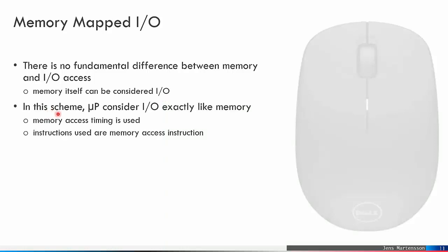In this scheme, the microprocessor considers I/O exactly like memory. The timing access is memory timing access, if you still recall our topic on memory read and write. The instructions used are also memory instructions, like store and load.